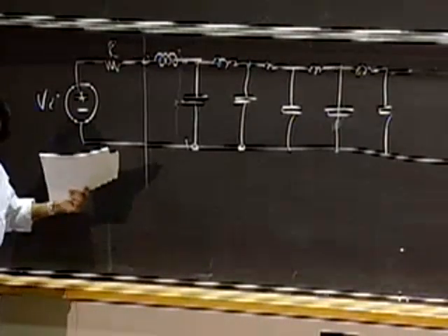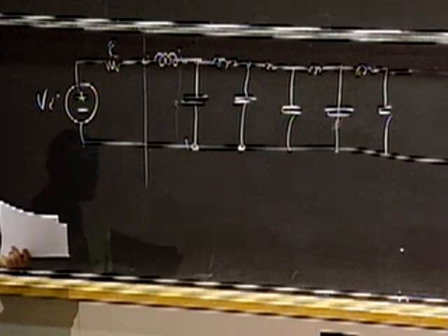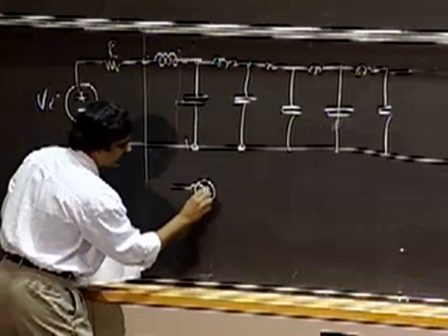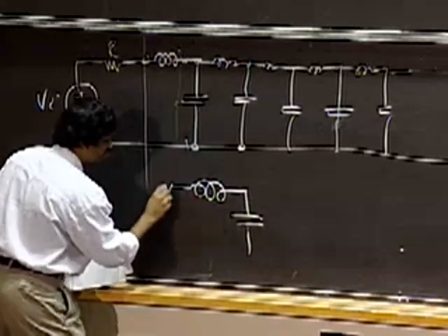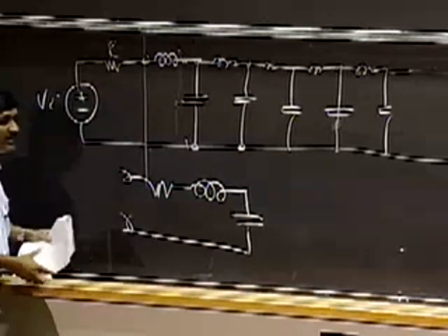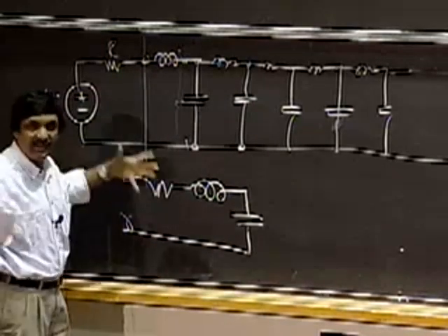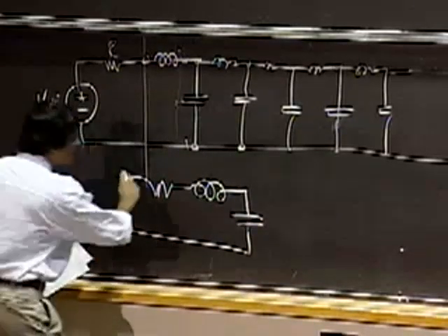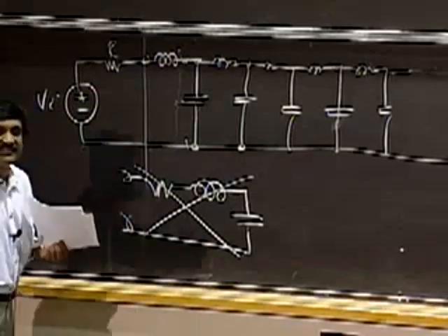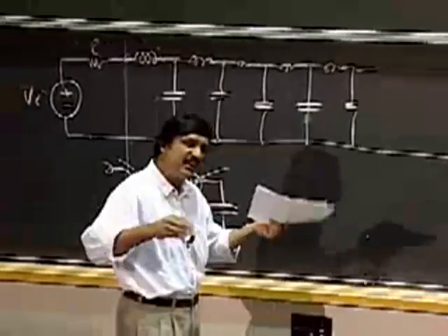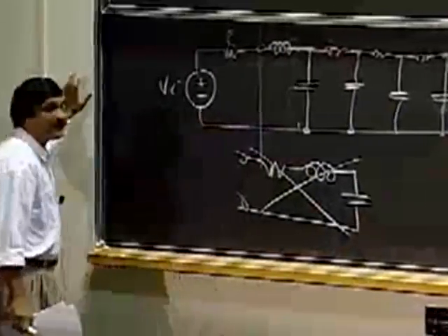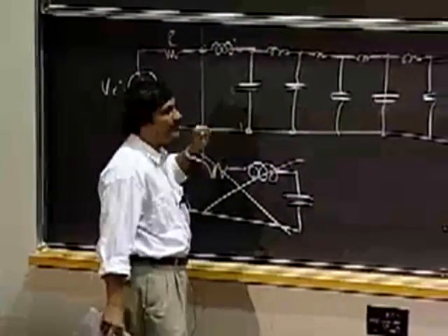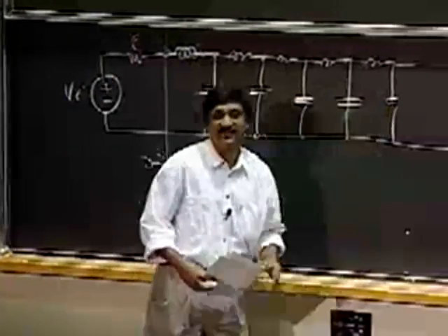Notice that in my lumped circuit abstraction, when we talked about the RLC model for the wire between two inverters, we lumped this thing into a model that looked like this. We lumped the resistance into a source resistance, all the inductors into a lumped inductor, and all the capacitances into a lumped capacitance. Now, I can do this when the signal speeds of interest are much slower than the speed of light, than the propagation speeds of electromagnetic signals. In this case, that is not quite true, and so we have to model it much more exactly.